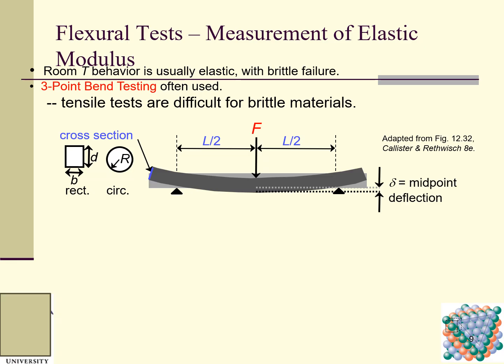And then we talk about the flexural tests for ceramics, and we use the flexural tests. Why? Because the tensile testing that is usually designed for metal alloys, ductile materials, cannot be used here, because ceramic is brittle, and if we apply the tensile stress, it will break. And then we use the flexural testing, and so this is the